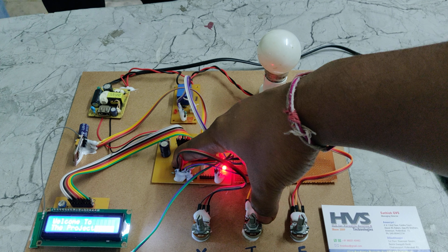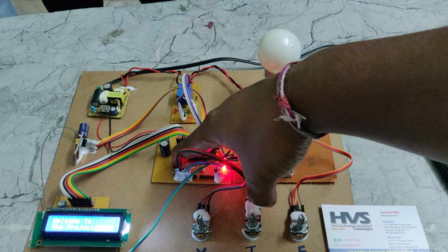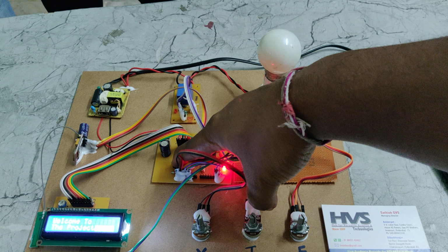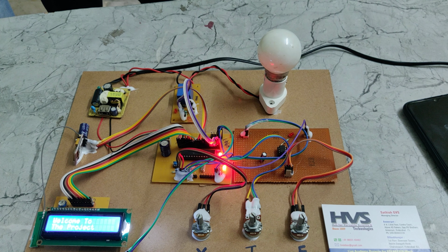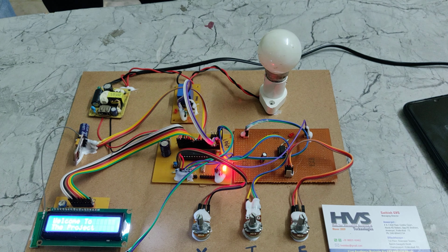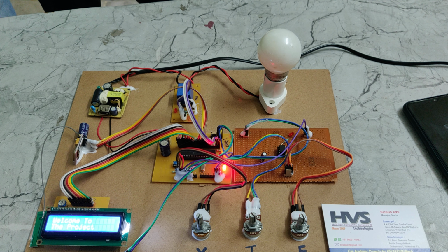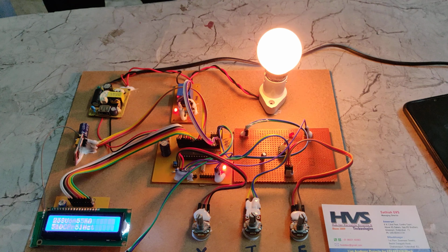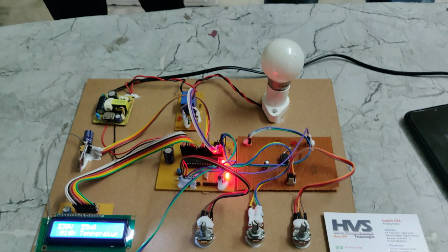We hold the microcontroller to block the communication until then; only then will the system execute the SMS service properly. Now you can release the switch after the SIM card gets the signal. On the LCD display we can see the parameters after SIM initialization is successfully done.